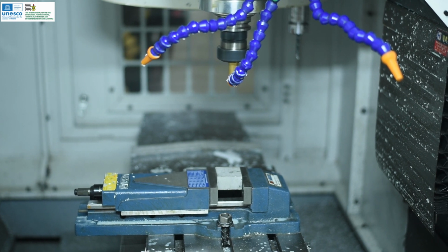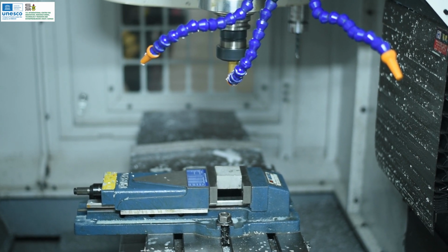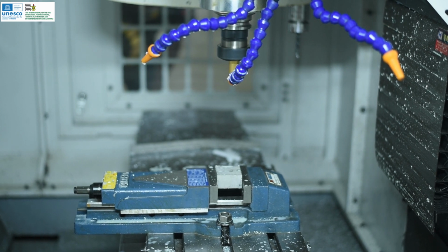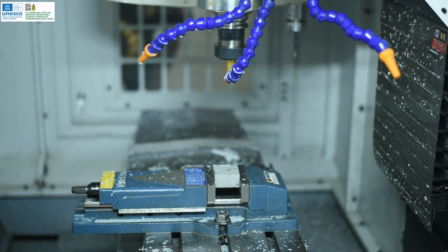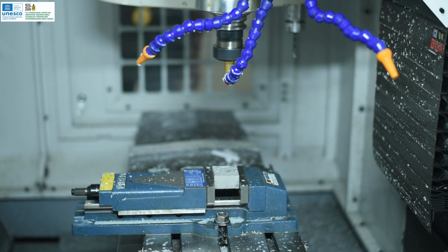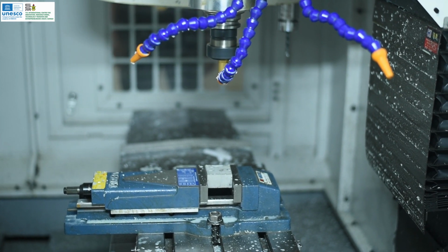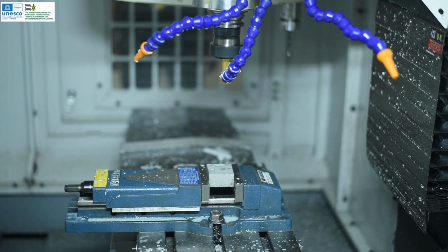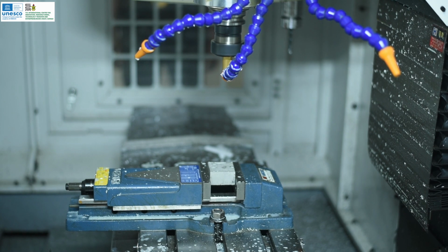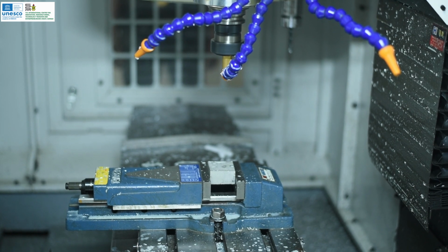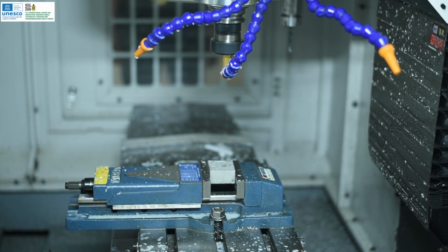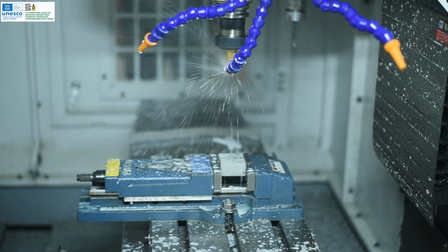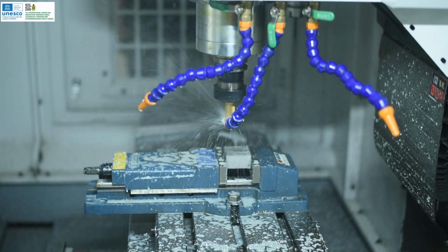The next thing starts our spindle, starts our coolant. We're going to wait for that coolant to flow and start coming out before we move on. Sometimes it takes a little while. We want to make sure we're not starting that program before the coolant starts to flow. So once that's going, we can keep moving down in our program.